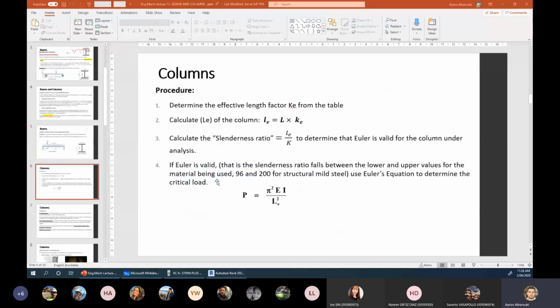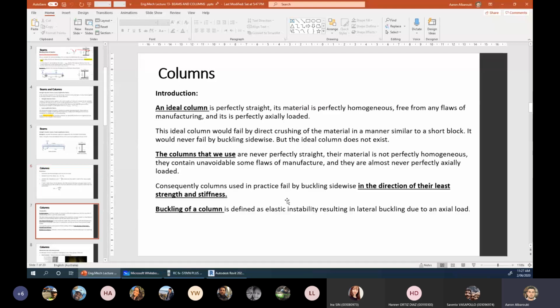And also we're going to talk about the slenderness ratio of a column. Slenderness ratio of a column, very important concept that will determine the effectiveness of this column in theory. It talks about the overall geometry of the column. Okay, these are the points. As soon as we calculate these small variables, everything else is exactly the same as what we know, and that will allow us to calculate using Euler's equation what we call the critical buckling loads. Okay, now in terms of buckling,